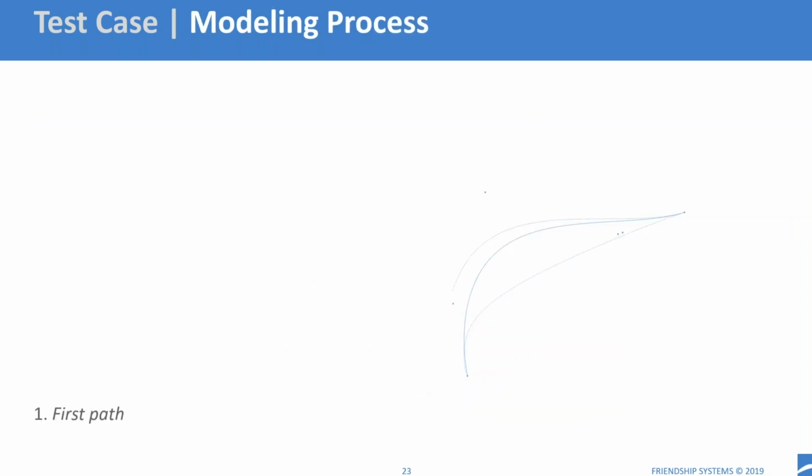So I would like to start with the modeling process. If we want to work on such a case, the first step would be to build the parametric model to be used in the optimization, with all the parameters that we want to be able to access and all the freedom of variation that we need during our optimization. And here we would like to model the part geometry, of course. We start by defining the paths of the two channels in the port. And this is the first path that we have designed here.